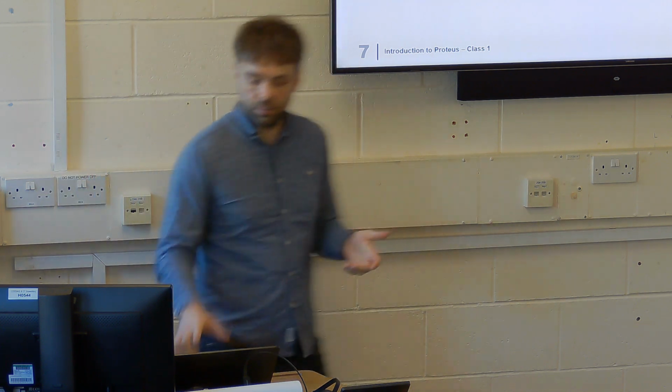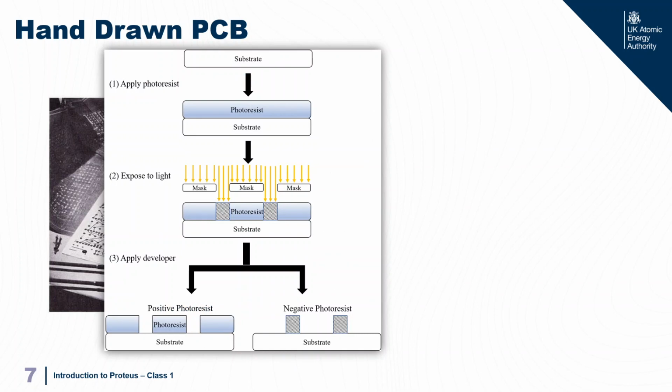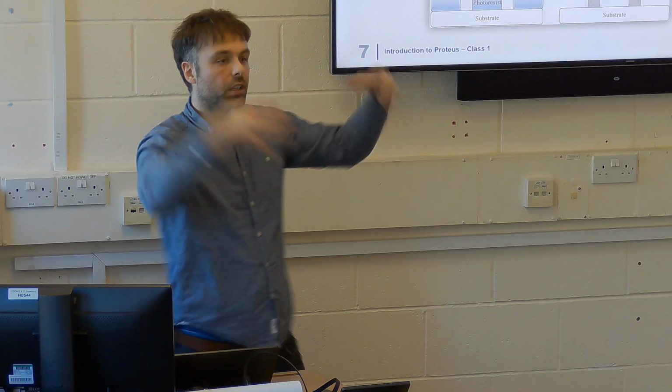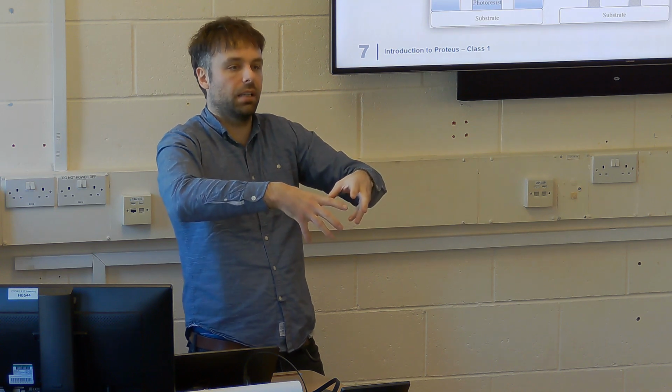That would then be used in a process called photolithography, where you get a copper-clad board, solid copper, with FR4 on the back. You would put a photoresist on it, and then you would use this mylar drawn sheet as a mask and direct light through it, and you'd expose all of the photoresist that the mask doesn't cover. And you can use lensing to shrink this image down to the size that you want, like an overhead projector, that kind of stuff.